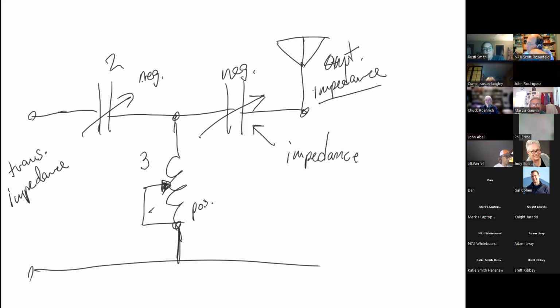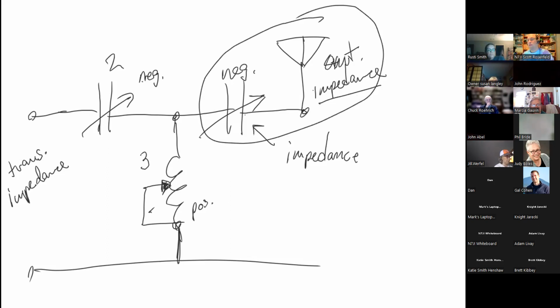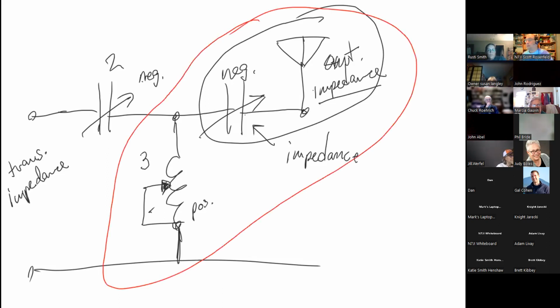What happens if we have an impedance in series with another impedance? Impedances are just like resistances. They add together. So now we have these guys in series with each other. Well, what happens if we then add another impedance, but effectively it's in parallel? So we then have a different formula. Like we had Z1 plus Z2.